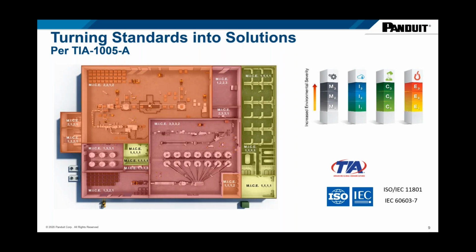Something you would normally do in the design, kind of rate these different spaces and say, here's an area where I'd like to run my cabling because it's more of a M.I.C.E level 1. And then here's another area where I know I need sensors in this area, I can't avoid it, and so now I need a more harsh product in that installation. What it allows us to do is have a better design and control the costs so that we don't need the harshest grade cable everywhere. We just need it where we have that M.I.C.E level 2 or M.I.C.E level 3.